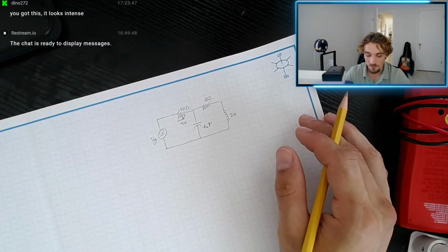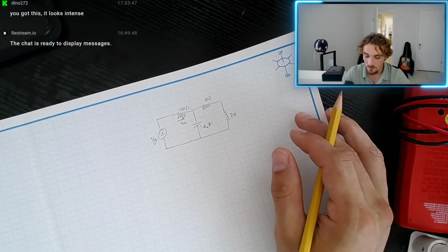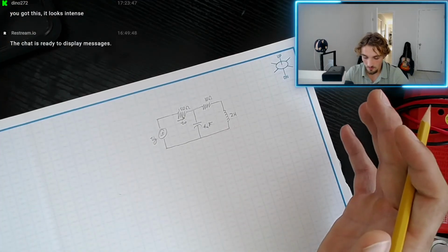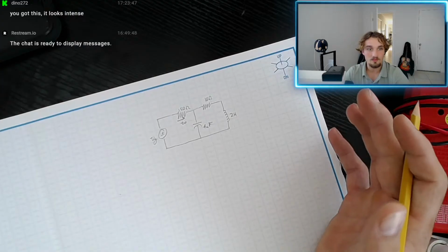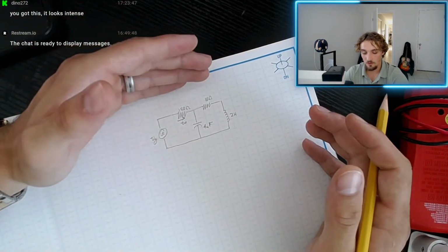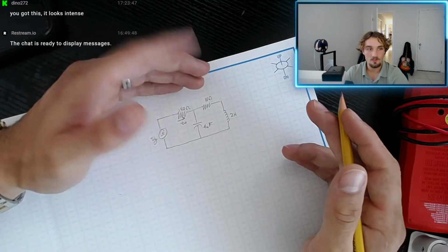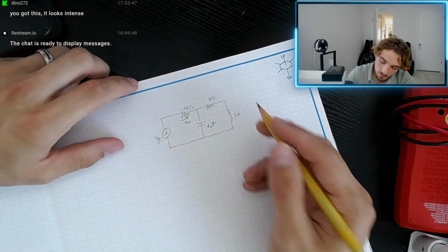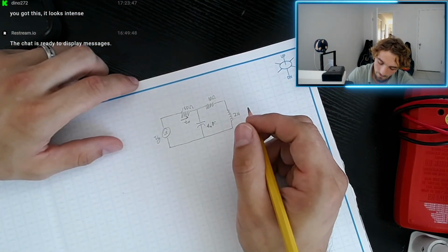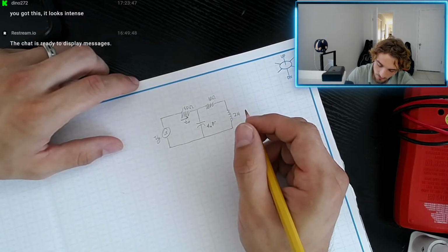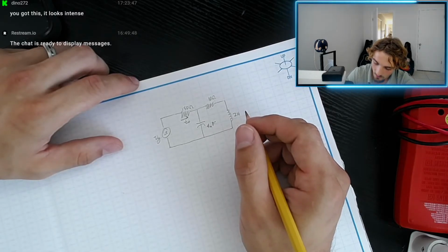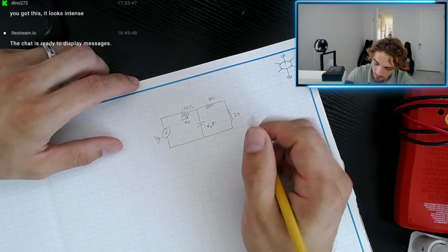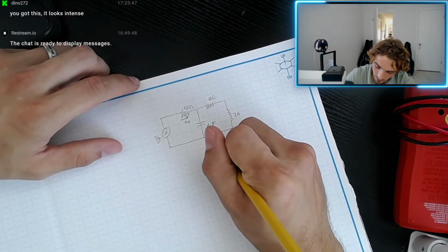To find the total impedance of the circuit, and then just divide VG by that. That's like Ohm's law. Am I not converting to the phasor? No, the polar coordinates. It's not absolutely necessary, but it does simplify it. But we're not even doing that yet. This is all just simple addition. Reciprocal. The other thing we can do is simplify that. Let's just start there.